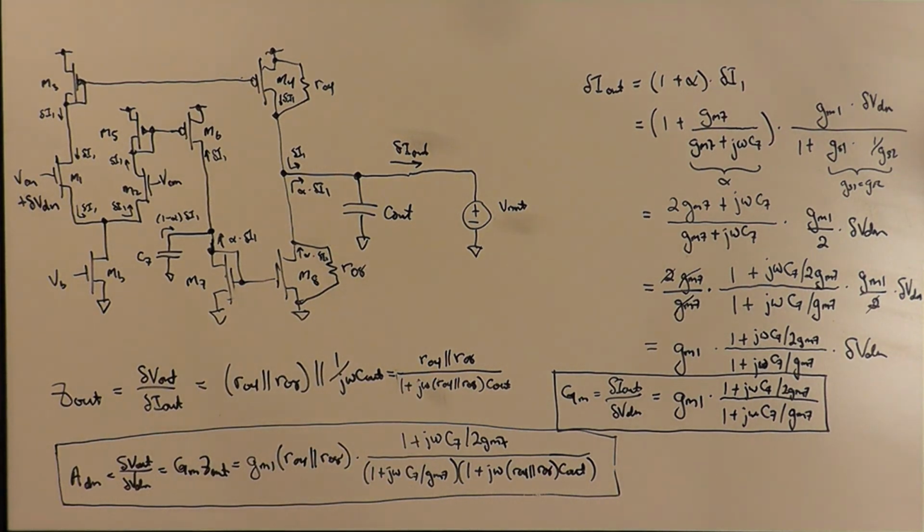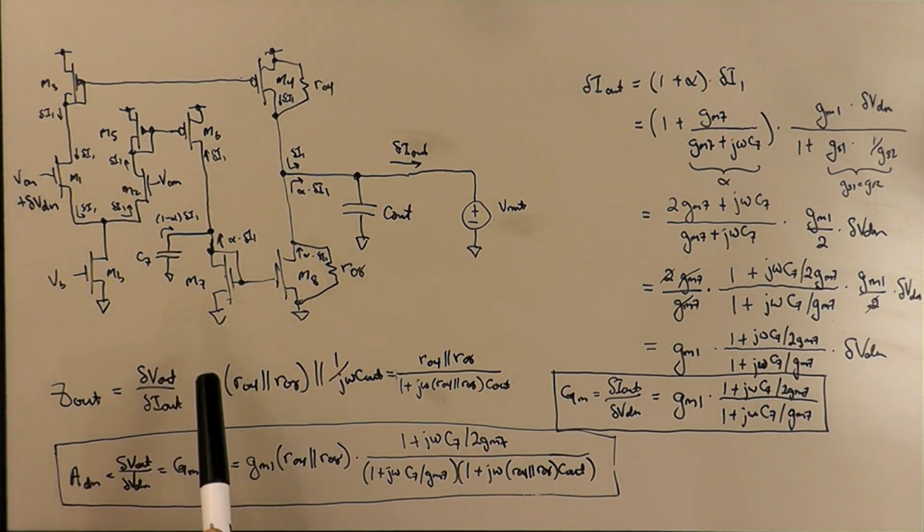And then maybe if we see something like an extra corner in the frequency response of a simulation that we're doing on the circuit, we can say, okay, well, this probably correlates well with the dominant pole that we see. But then, we might see something else and wonder, okay, now what could I add to the circuit to account for the various other twists and turns that the frequency response takes, whether it flattens out because you hit a zero, or whether it starts dropping off at a steeper rate because you hit a pole or something like that.